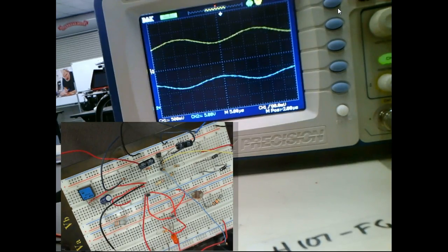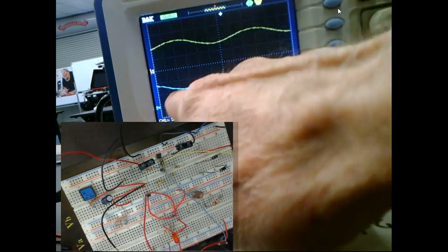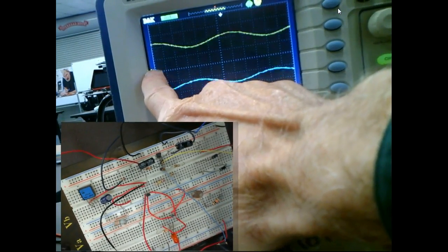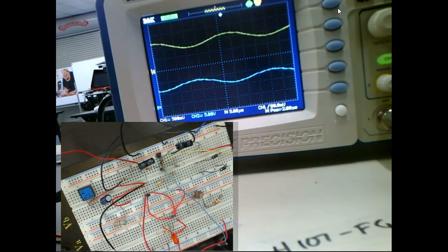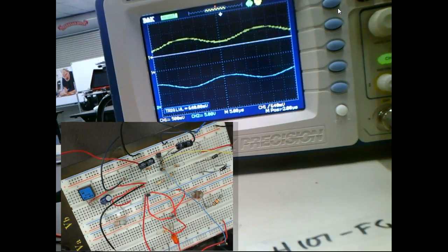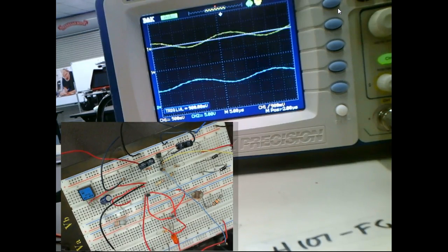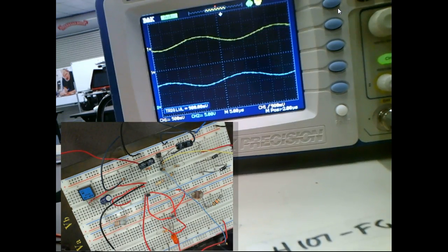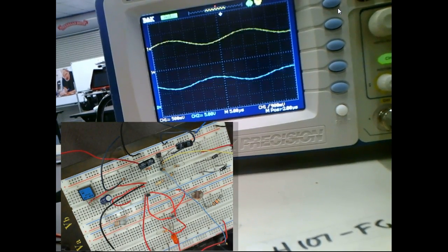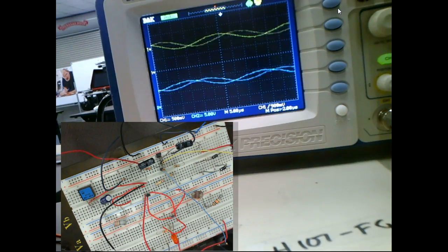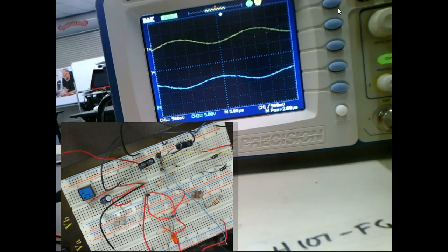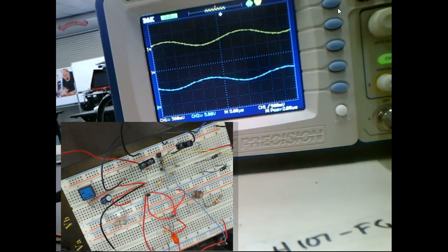But what's actually happening is here's 0 now, right? Y'all see 0? And so this AC signal is riding on. So what we did is we brought that through the capacitor. So I had AC on the other side of the capacitor. Now what the AC is doing is adding and subtracting from my base voltage, right? You understand that? So it's actually riding on top of DC, our base bias voltage.